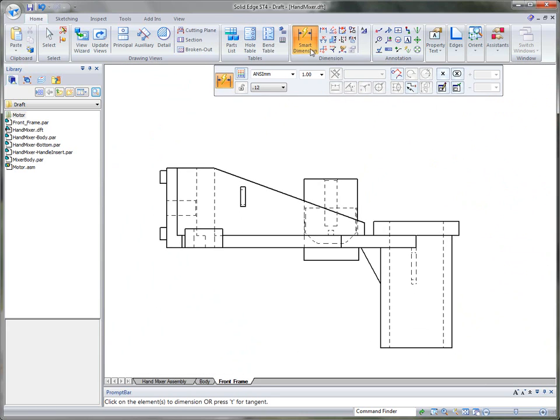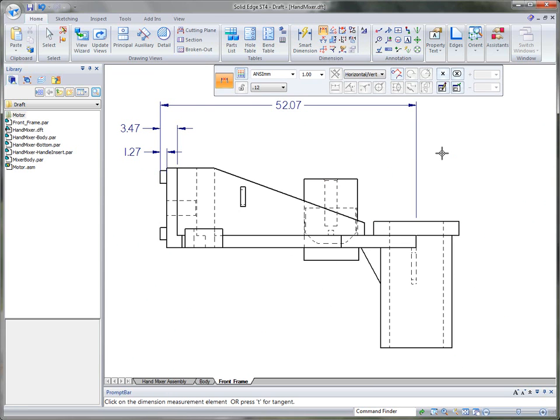Now, let's take a look at another dimensioning tool, one we call distance between. If I pick, for example, a couple of elements, and then I pick this one, maybe I want it off to the left, and then I come over and pick this center one, that works really well. Now if I right mouse button click, I get out of that particular stack. Then I can come over and maybe dimension from here to here, and then right click to get out of that stack.